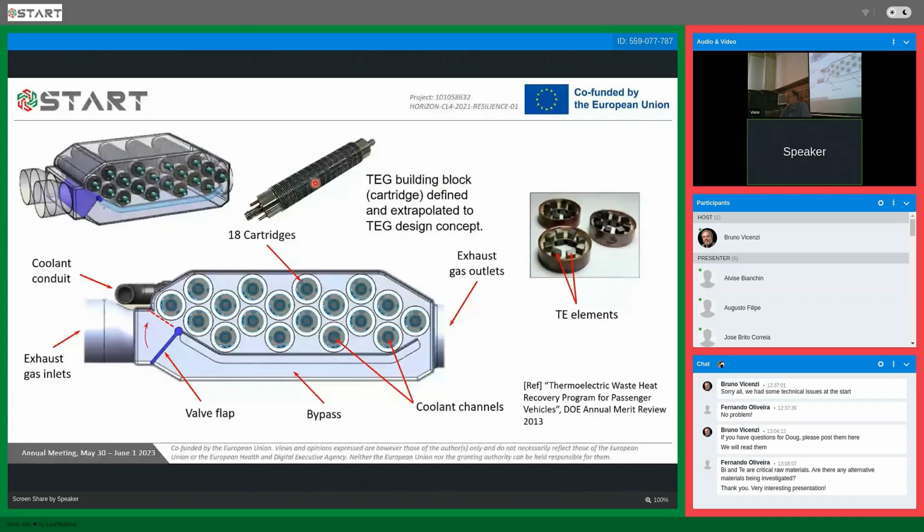TAGS also had a limitation of about 400 degrees Celsius. Magnesium silicide is somewhere in the 400 to 500 degrees Celsius range. Lead telluride can be used to about 500 degrees Celsius. Skutterudite, in different configurations, could be used a little bit higher. Nothing as high as silicon germanium, which I have seen discussed for use up to almost 1,000 degrees Celsius with some of JPL's work in that area.